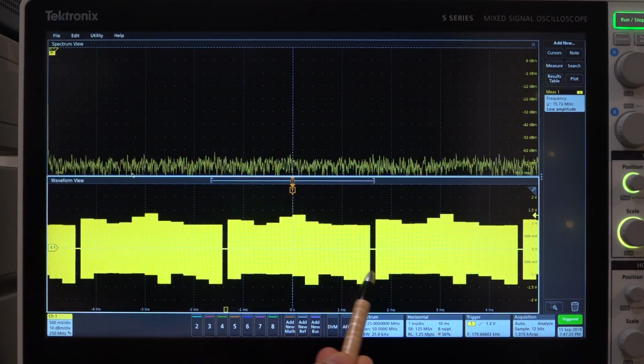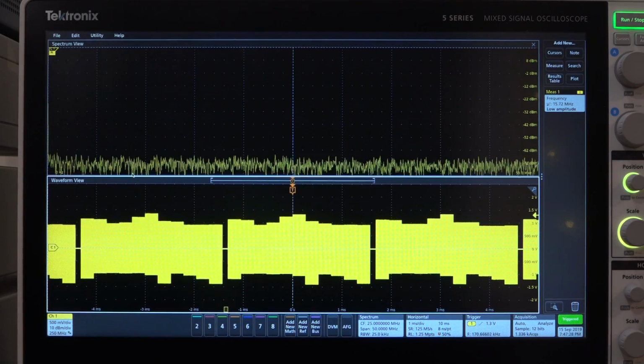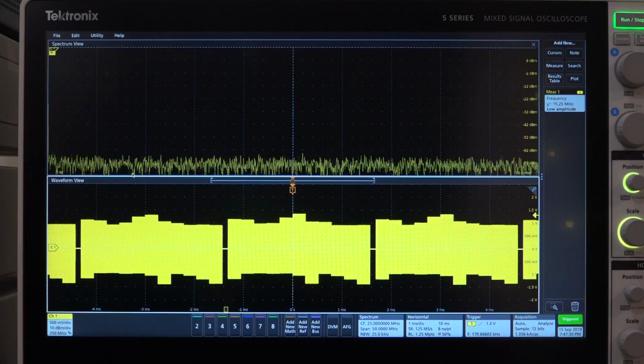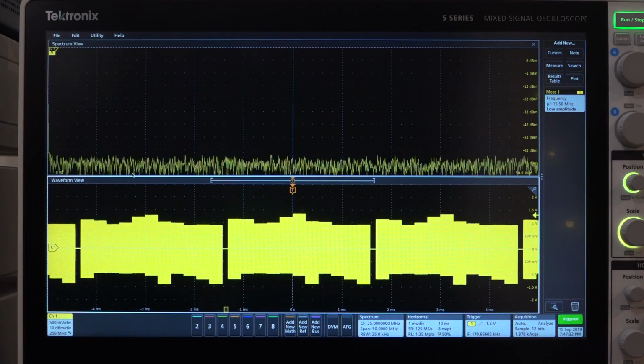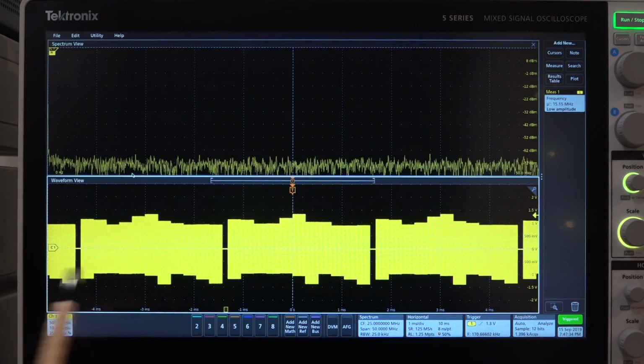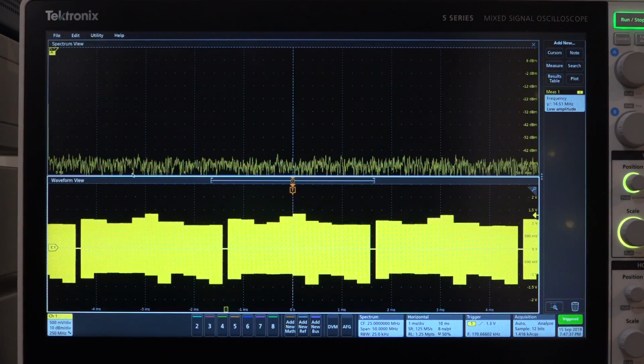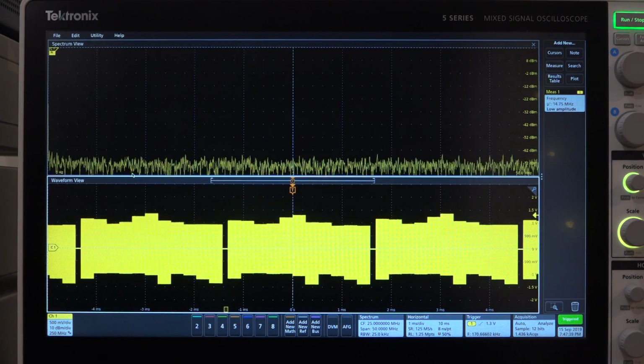And you can also see the blanking regions between the different sections of the sequences we have created, which is a difference between the duration of 1 segment and 1 millisecond. So that all makes sense, and I'm using those differences in order to create a hold-off trigger so the waveform isn't moving around all over the screen.